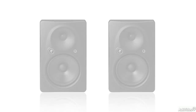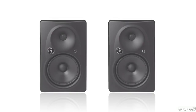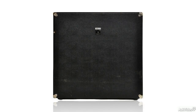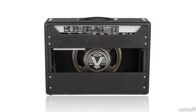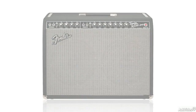While full-range speakers, like studio monitors, usually incorporate at least a two-way design, woofer and tweeter, some speakers use only a single driver. The speaker cabinets that are used for electric guitar and bass amps are most commonly a single speaker, an 8-inch, 10-inch, 12-inch, or 15-inch dynamic model, in either an open-backed or a closed-back cabinet. Since they have no high-frequency element, and the cabinet, especially open-back cabinets, may not help much with the low end, these speakers have a pronounced mid-rangey response.